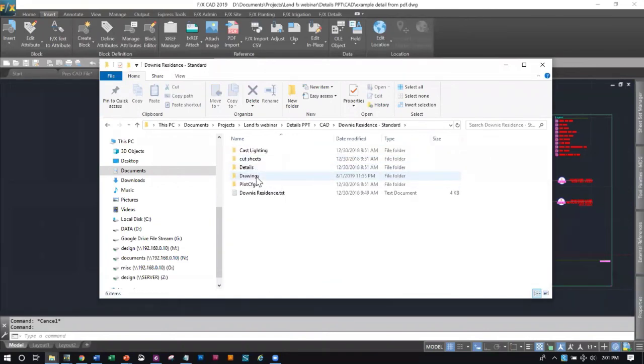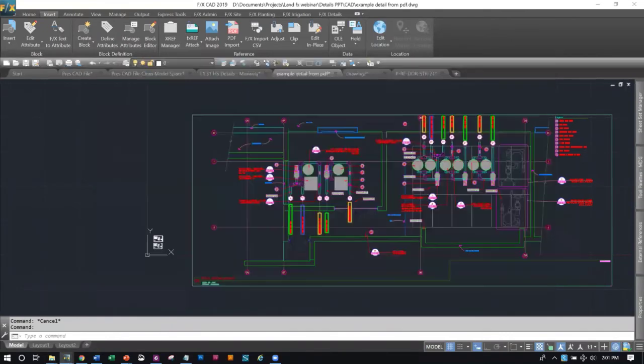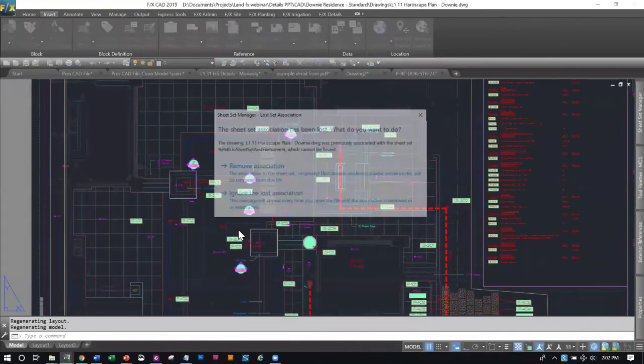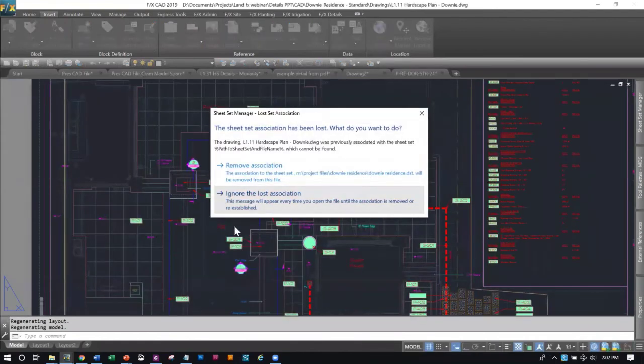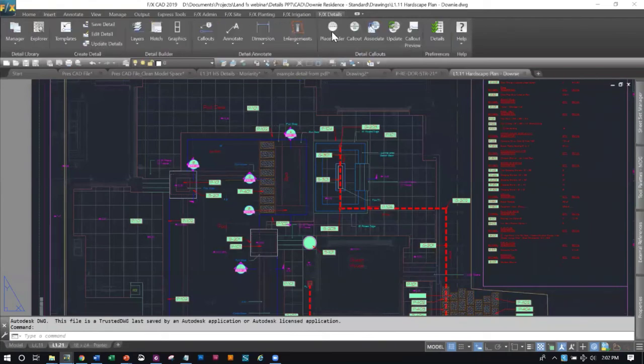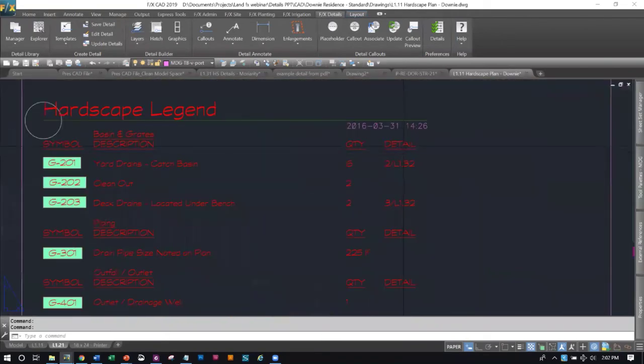And I can demonstrate that benefit, or the benefit that I like the best, and that is with the shortcut keys. The nice thing, if we go to the FX detail ribbon, you have edit detail. So if you take the time to fully integrate ref notes, your hardscape, and you tie everything in with your detailing system, what Paul is talking about, when you run your ref note schedule, you can include a detail.